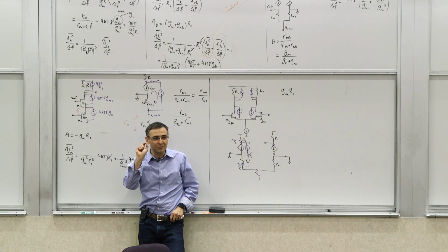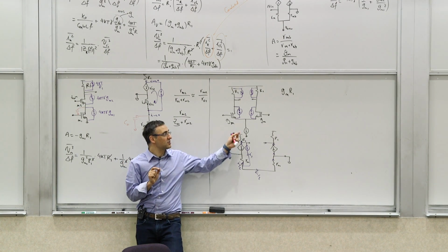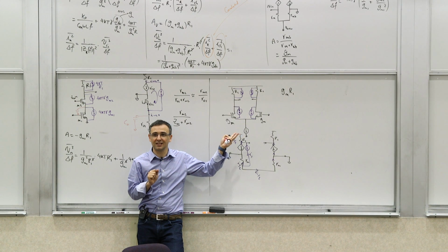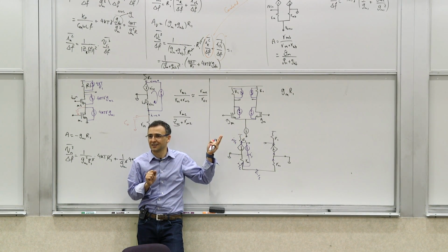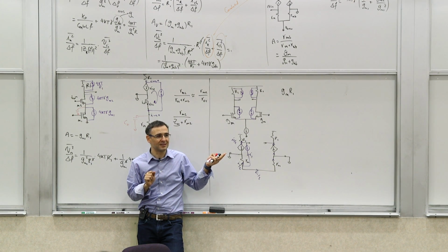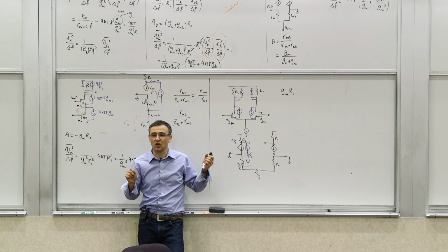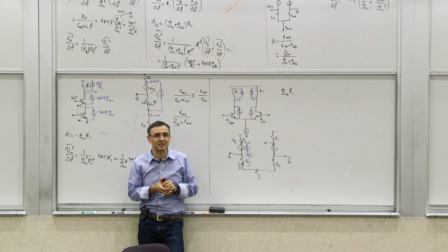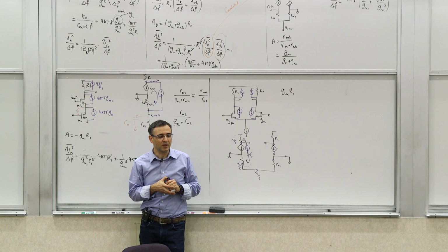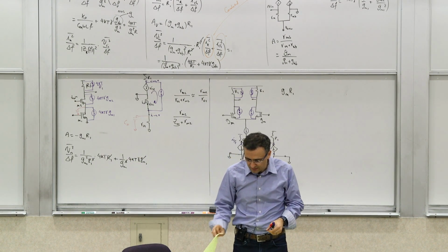If you're intrinsically limited by noise, though, this stage is not only not advantageous, it actually has a disadvantage, because it generates more noise for the same amount of gain. And those kinds of amplifiers you see a lot of times, they're actually done as single-ended, or things that are done for radio astronomy or cryogenics and things like that. So a lot of times you will see them. You don't see a lot of differential design there, because of this effect. Okay? So that's for a differential.